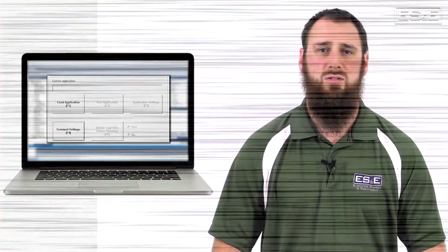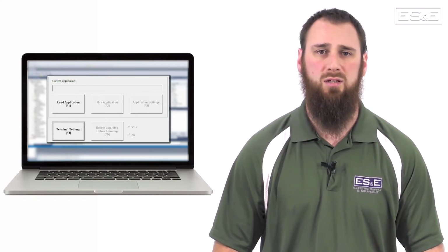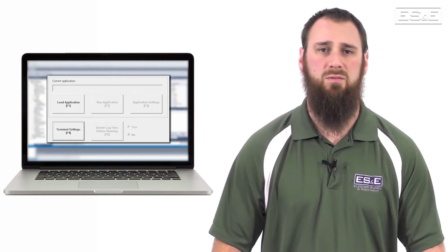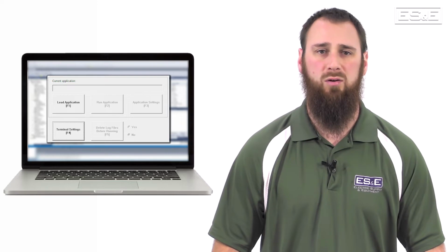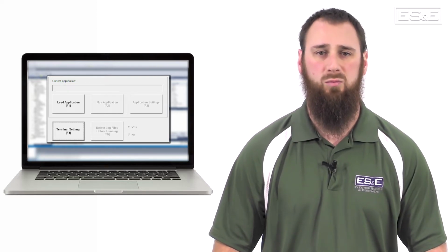on your PC. FactoryTalk View Studio automatically installs ME station that allows you to replicate the PanelView on your computer. The only thing that would be different is if you are launching something from memory or pulling anything from the PanelView memory. The memory location will be different.